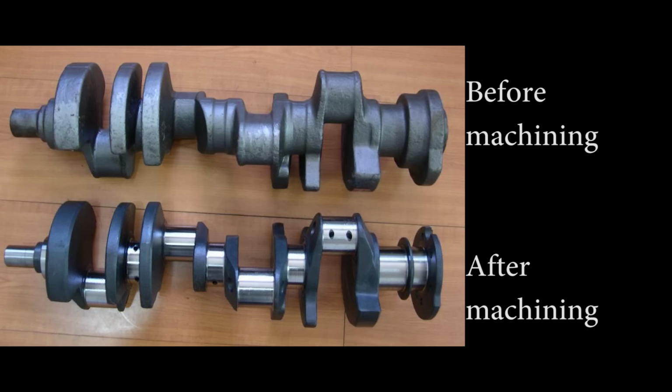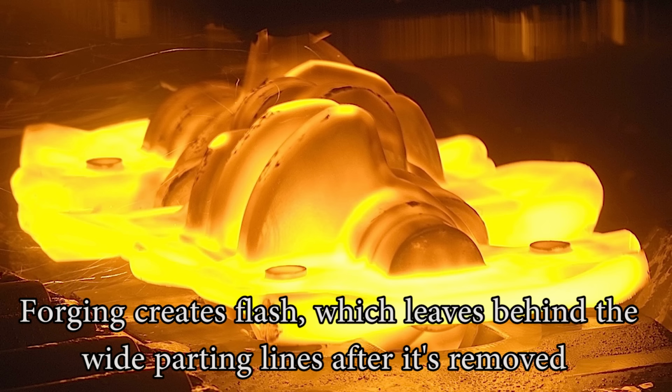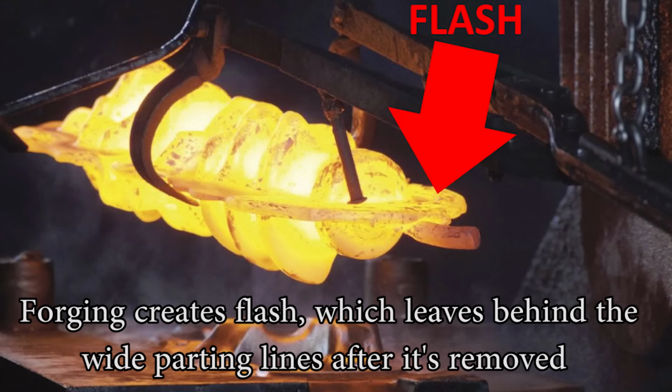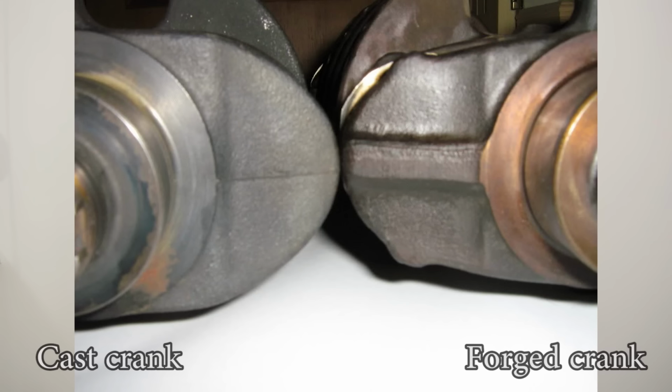You can tell a crankshaft is forged by looking for signs of grinding on it. Now, during the forging process, excess material known as flash comes out of the forging dies. This then needs to be ground away, leaving behind a telltale sign of a forged crankshaft.